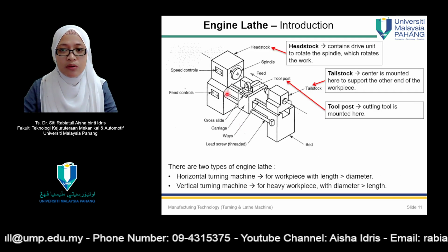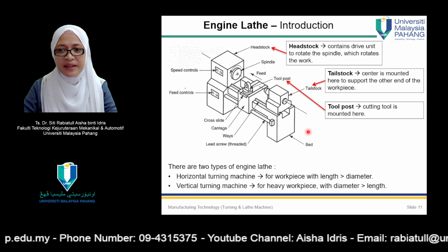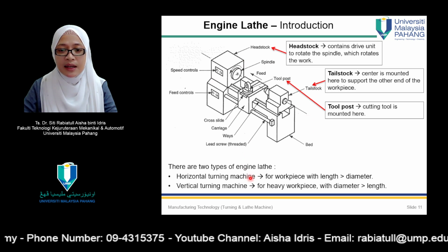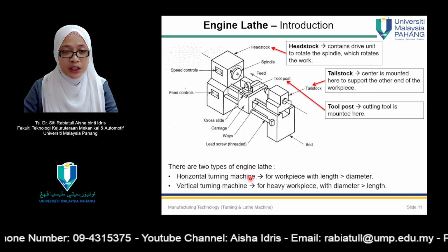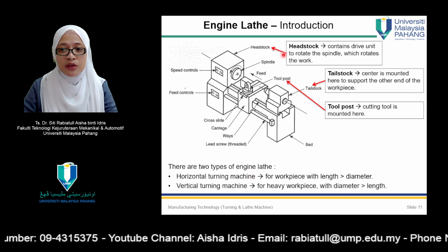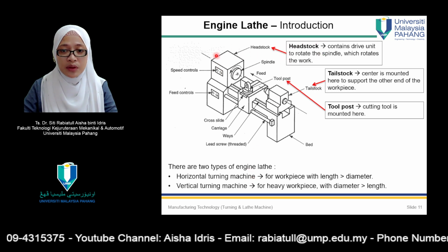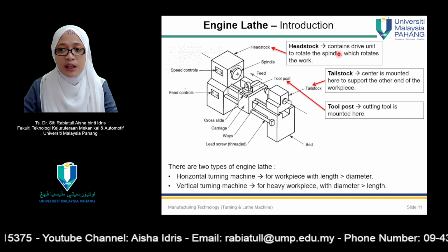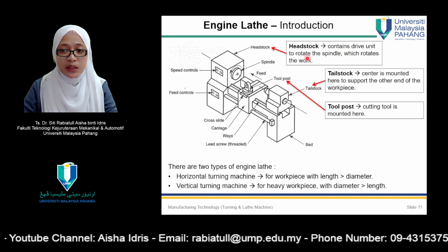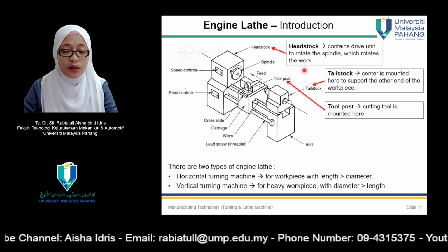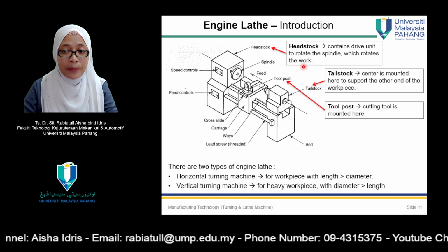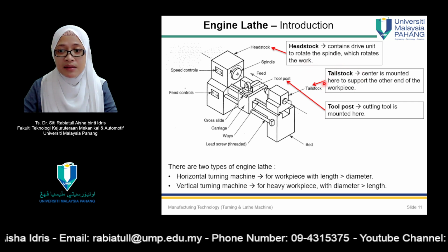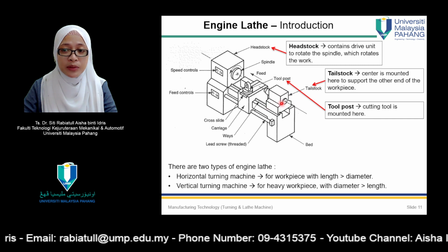So this is what a lathe machine or engine lathe looks like. You can see that it is divided into several sections, for example, the headstock. So this is the headstock. It contains a drive unit to rotate the spindle, which rotates the work. Work represents the workpiece. And then you can see the tailstock at the end of the machine,